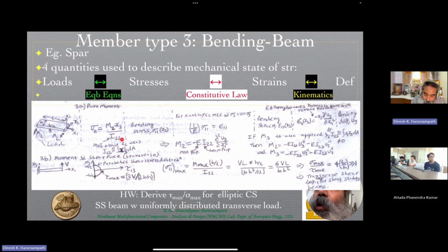And instead of the torsional constant J that we had there, we have a moment of inertia I. Once again, this can be done very, very simply. This can be proven by taking an infinitesimal element. If you take this beam that is bending, and let's say in this example this is x3, then we take a small infinitesimal element over here. We know the stress that is acting is a function only of x3. So within that thin infinitesimal element, the stress is constant.